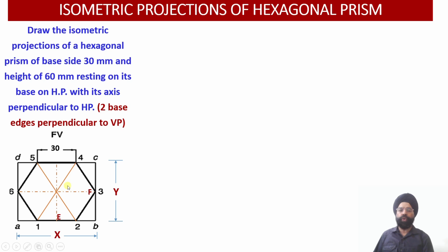So in order to draw this hexagonal shape in the isometric projection, we have to inscribe this geometric construction of the hexagon, which we have already drawn to true scale, into a rectangular shape. So this is a rectangular figure ABCD, which we have drawn to inscribe this hexagonal figure. Now this rectangular shape will first of all be drawn onto the isometric projection using the isometric distances.